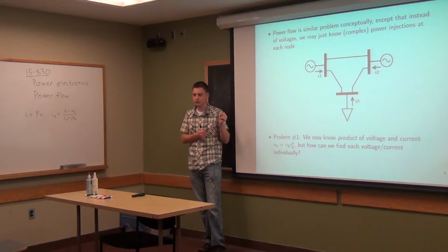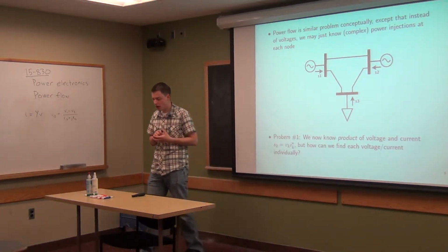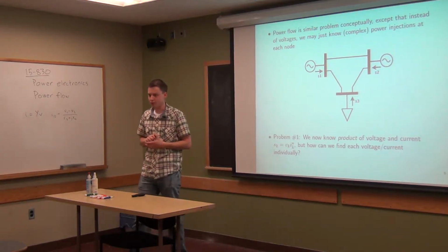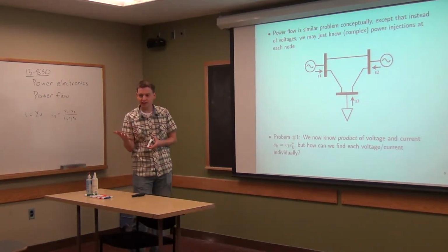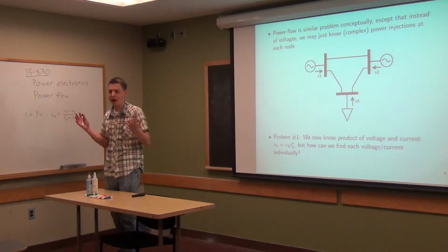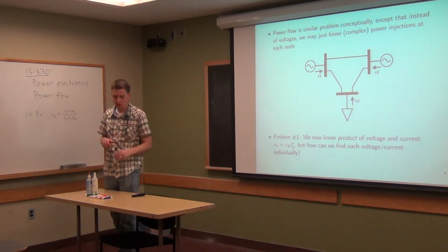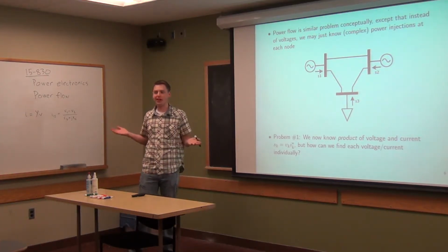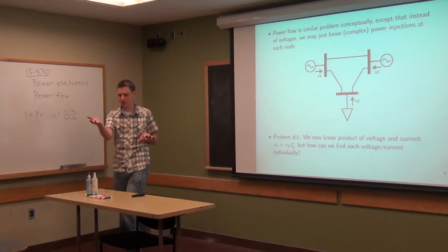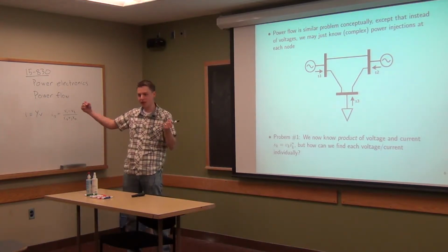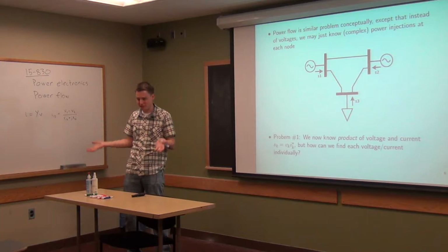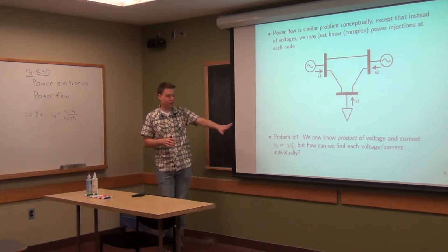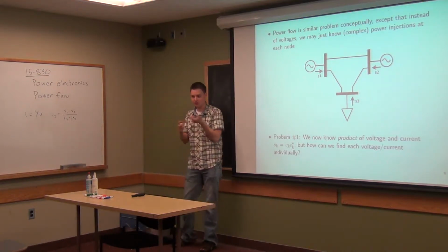You can't put any sensor or measuring? So you could put sensors on it. If you want to talk about measuring it, you could measure current, certainly. But the question about this is much more predictive rather than, tell me what's happening in the existing system right now. What you want to know is, if I turn on my generators like this, what's going to happen? I don't want to have to run it to find out, right? Because if your constraint is that you can't have too much current flowing over this one line, for example, you don't want to just start turning them on and then wait till the line disintegrates before you find out what's happening. The goal here is actually to predict when you turn on all these different things, what's going to happen.